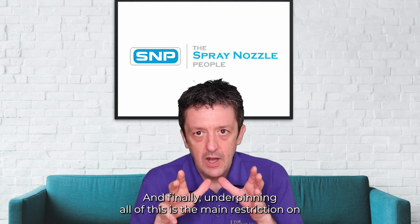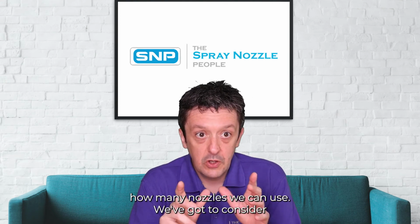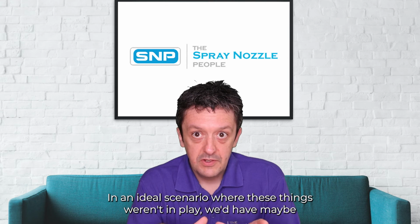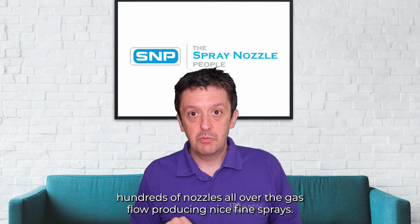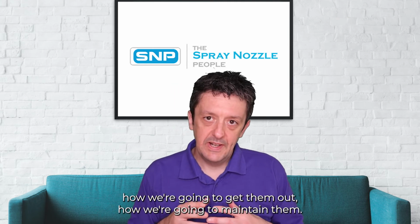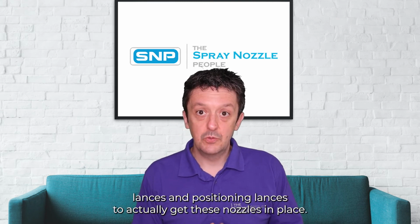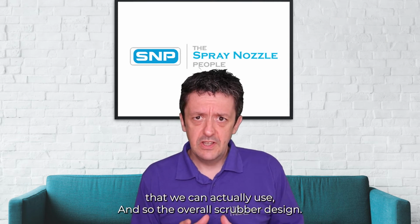And finally, underpinning all of this is the main restriction on how many nozzles we can use. We've got to consider maintenance and the retraction of those nozzles for maintenance. In an ideal scenario where these things weren't in play, we'd have maybe hundreds of nozzles all over the gas flow producing nice fine sprays, but that just isn't practical. We've got to consider how we're going to get the nozzles in, how we're going to get them out, and how we're going to maintain them. So we're going to need suitable lances and positioning lances to actually get these nozzles in place. That can have a really big influence on the number of nozzles that we can actually use, and so the overall scrubber design.